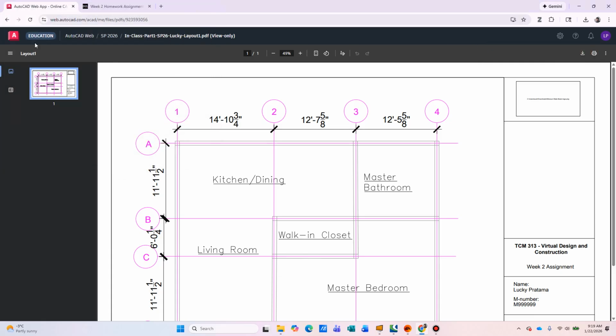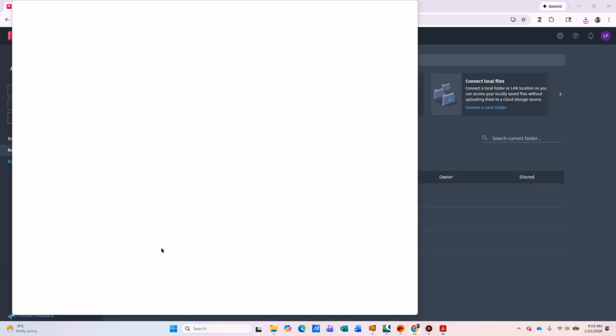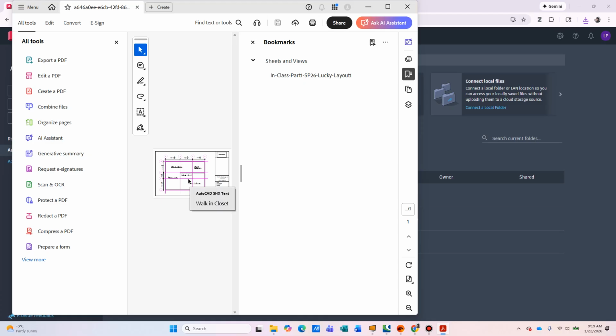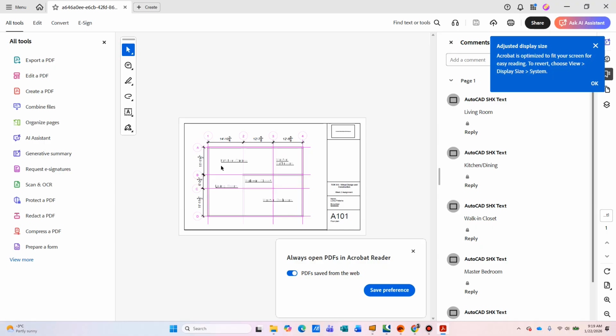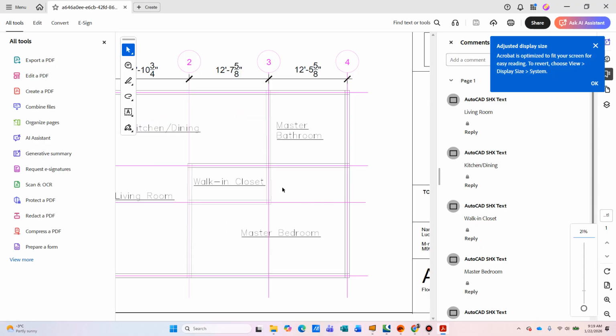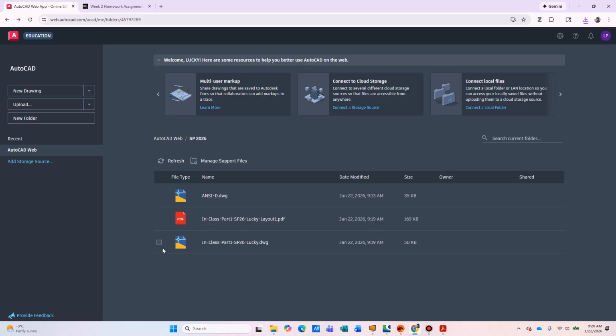All right. Next, if you want to download the drawing, you can see here that the grid lines are not going to be visible. If your grid lines look funky, that's fine. If you want to download the DWG file, in your main menu, put a check mark on your project and hit the download button. Then that's going to download the DWG file.